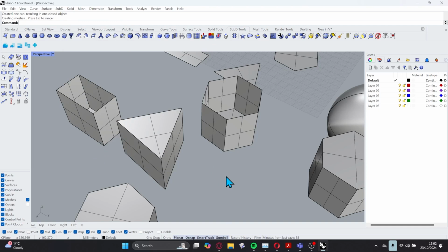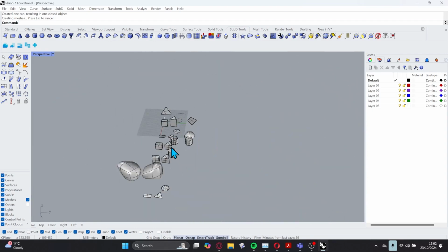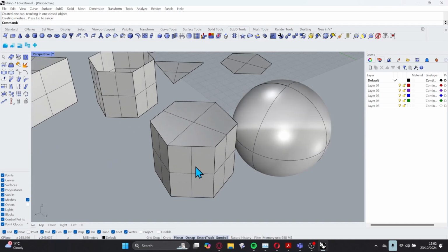Now, Rhino works forwards, but it also can work backwards. Let me explain what I mean by that. Do you remember how I said I can create a curve, and from that curve I can create a surface, and from that surface I can create a solid? I can also extract curves from surfaces. I can extract surfaces from solids. Okay? Let me show you how I would do that. Let's say I'm here in my model and I want to extract this face here.